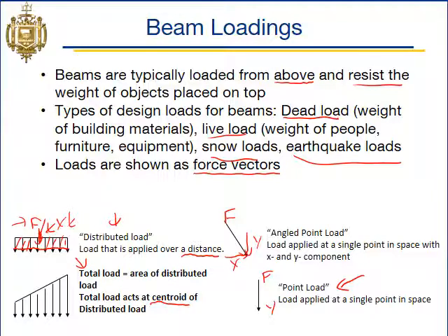If you had to do the equivalent load for this more complex one here, you could break this into two shapes, and you could even model this as two forces: the distributed load from this rectangular piece and the distributed load from this triangular piece, right? So this one would act there, and that one would act there. Or you could find the centroid of this whole thing and the area under this entire curve and model this as one point load for your reaction analysis.